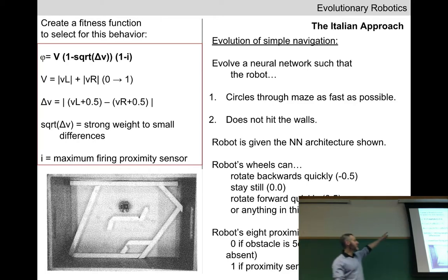So if we had just summed things in V, we wouldn't have that problem, right? So if we just said VL plus VR, forget the absolute, we're selecting for forward travel, and as long as we avoid collisions, we're probably good. But they didn't want to restrict the robot to just forward travel. They wanted forward and back, so they said absolute. And then evolution, I'll bet you the experimenters originally had just the first and the third term. And evolution is smarter than all of us.